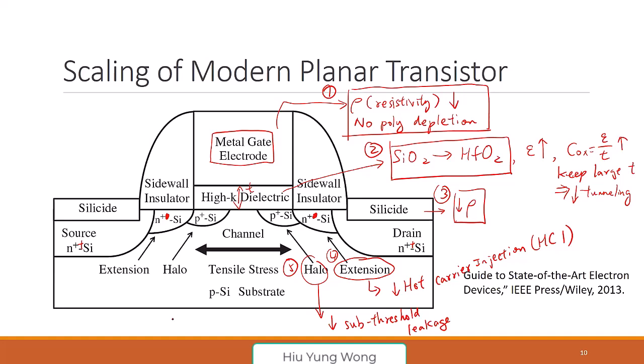We start going to SOI and also FinFET. And then we realize one thing is gate depletion, resistivity. And the other is that the threshold voltage is no longer good for FinFET, because the work function for the N plus and P plus poly are very close to the conduction and valence band. If you do some calculation, it's not good for FinFET, right? Just trust me. And then they start using metal gate again.